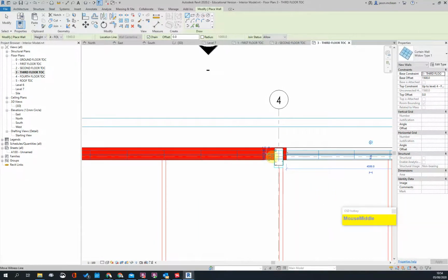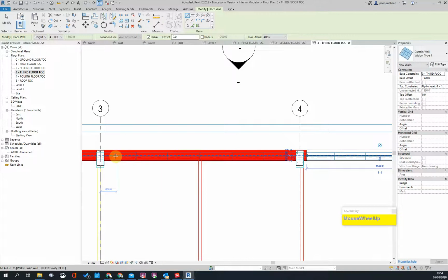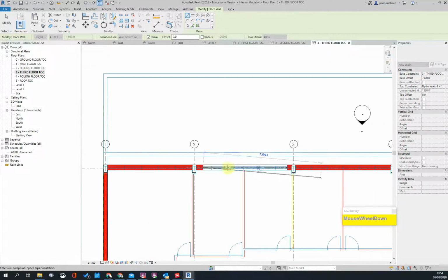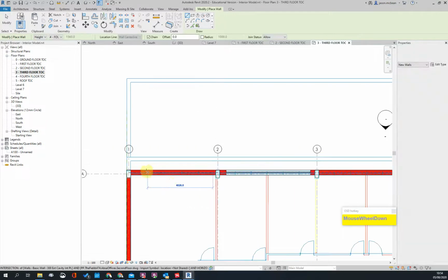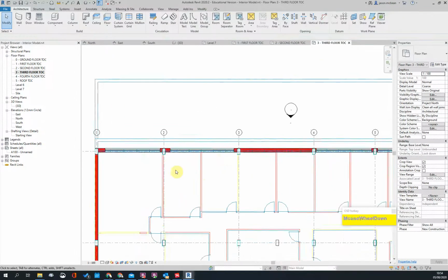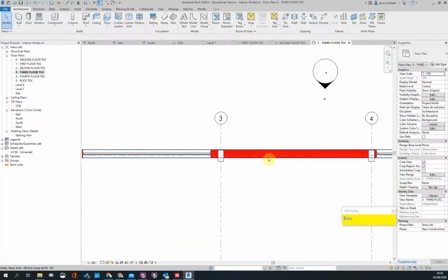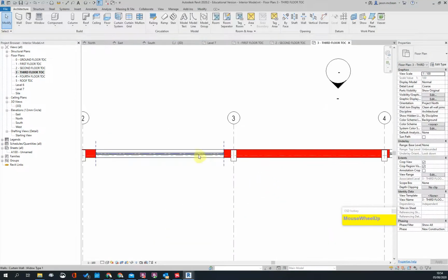We're going to align everything. Once the AutoCAD drawing's out, we can start fine-tuning these things better. Okay, that one didn't embed in the wall correctly, so that one I'll need to sort out. So I'm going to go to VG, switch off that for now. So here we've got an embedded one somewhere along here, so create similar.